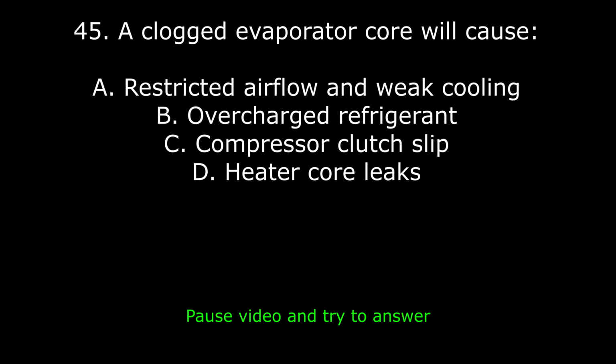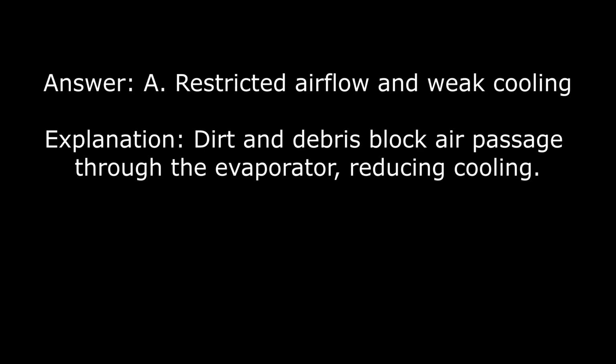45. A clogged evaporator core will cause: A. Restricted airflow and weak cooling. B. Overcharged refrigerant. C. Compressor clutch slip. Or D. Heater core leaks. Answer is A, restricted airflow and weak cooling. Explanation: dirt and debris block air passage through the evaporator, reducing cooling.